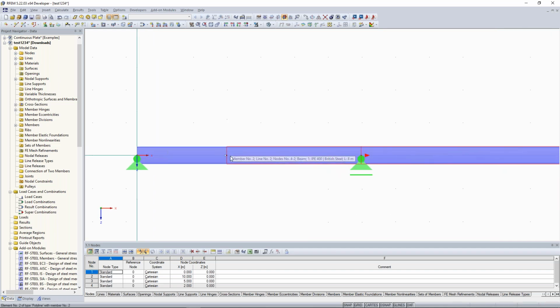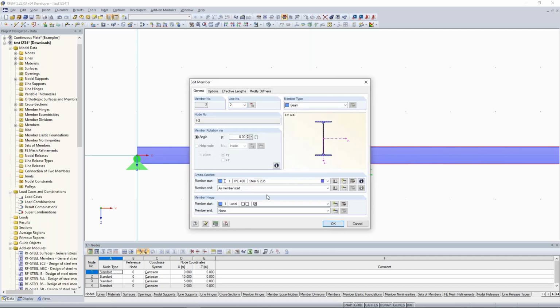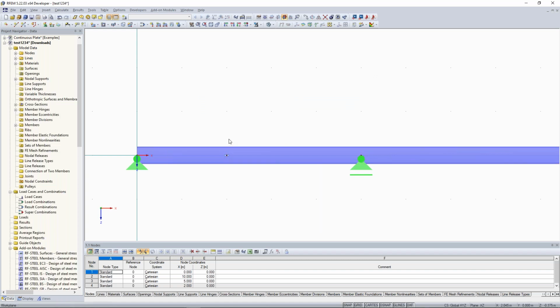And when you would have an additional hinge here, like here again, then it would be unstable, because you have a hinge chain, because we have two hinges. So keep that in mind when you have two parts of members. It's okay to have just one hinge in order to consider the zero moment here. Two hinges would cause a hinge chain.